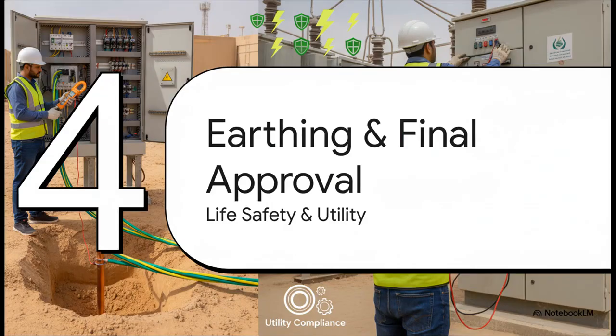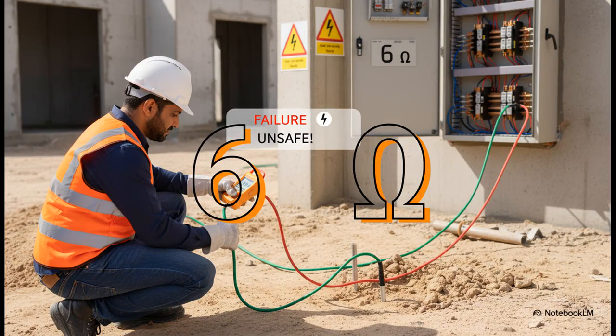Okay, we're at the finish line. Let's talk about the final checks that happen right before the system gets energized. This is where inspectors scrutinize earthing for life safety and power factor for the utility company. So imagine this. It's final inspection day. The engineer comes out, connects their earth resistance tester to your system, and gets a reading of 6 ohms. That's it. Project fails on the spot. It's considered unsafe. A reading that high means the system can't get rid of a fault current safely, and that creates a deadly shock risk.